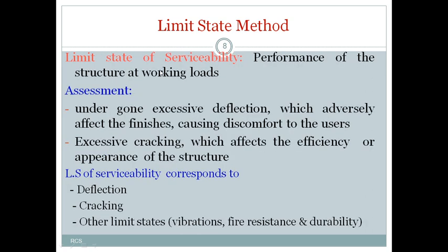Another limit state is serviceability. It gives the performance of the structure under working load. As I said, we will design the structure by using ultimate load and we will check the performance of the structure based on their working loads. And this serviceability can be assessed under excessive deflection and excessive cracking.